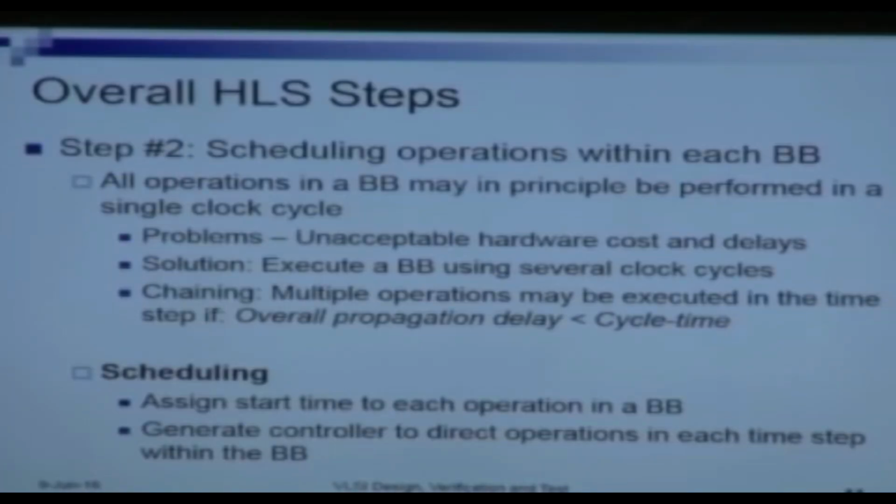When we divide things into different time steps, I can share the same resource at different time steps, which is not possible if I do it within a single clock step. Right? And also, it will increase delay. Why? Let us say this clock is not only feeding this basic block here, this clock is possibly feeding many other basic blocks in different parts of this module, and in other modules of the whole application.